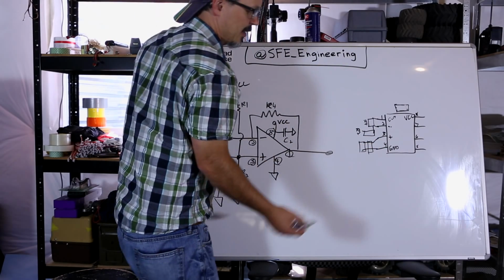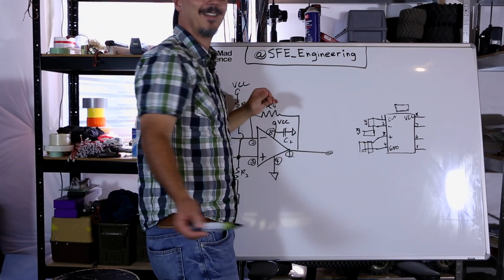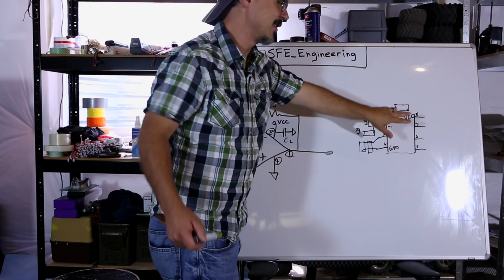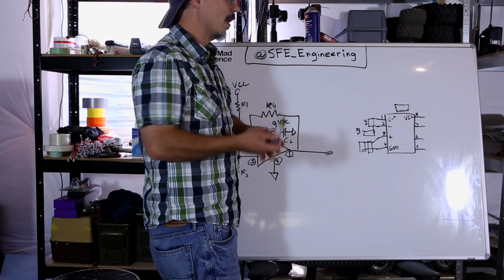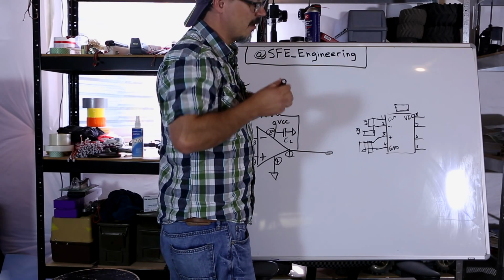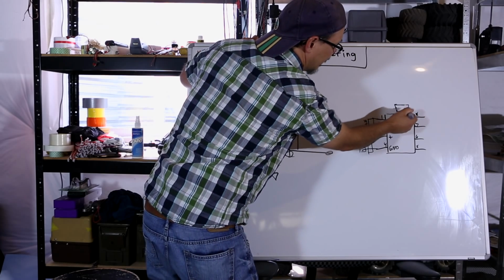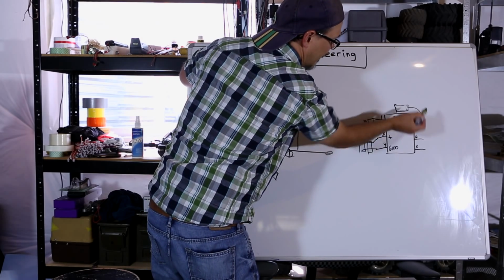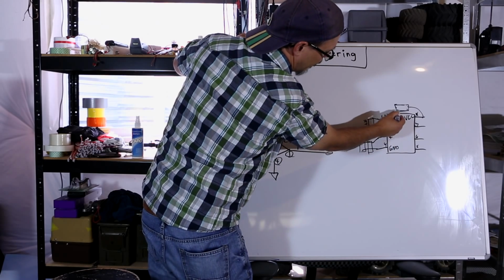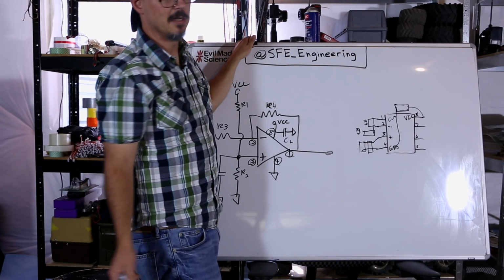Now, on the SOIC package, you've got VCC on one corner and ground on the other corner. So it's a little difficult. If you're putting components on the opposite side of the board, this is an easier thing to do. Most of our boards are single-sided that way. So it's a little trickier. So what we've done in the past is we'll put the filter cap up here and run that to there. And then, if all the traces for this op amp are coming off over here, you can run a trace down over to here. And that's about as minimized as you're going to get.